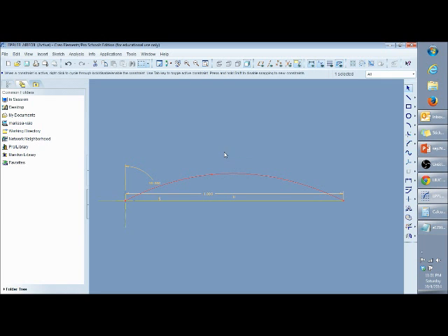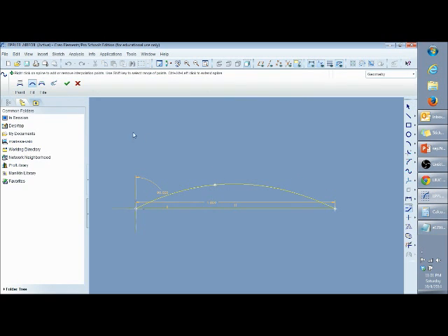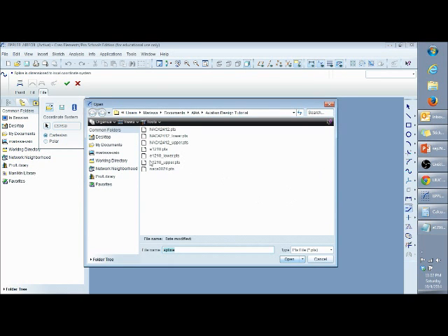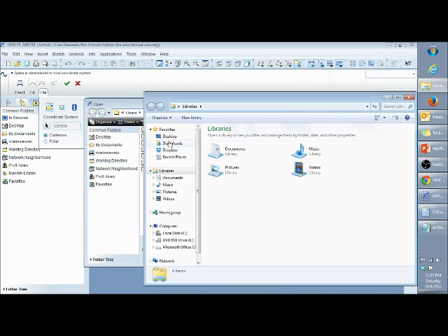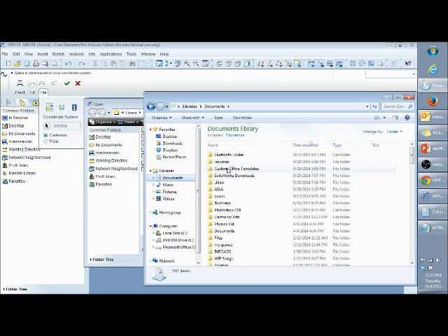And to modify it, hold the right click button, just like I did. Make sure you have this spline curve selected. Go to Modify, then File. It'll ask you to select the coordinate system, so select the coordinate system that you just created. Then go to this button right here, and since we have the upper curve, select the upper points. And a very important note: let me find that upper file real quick.